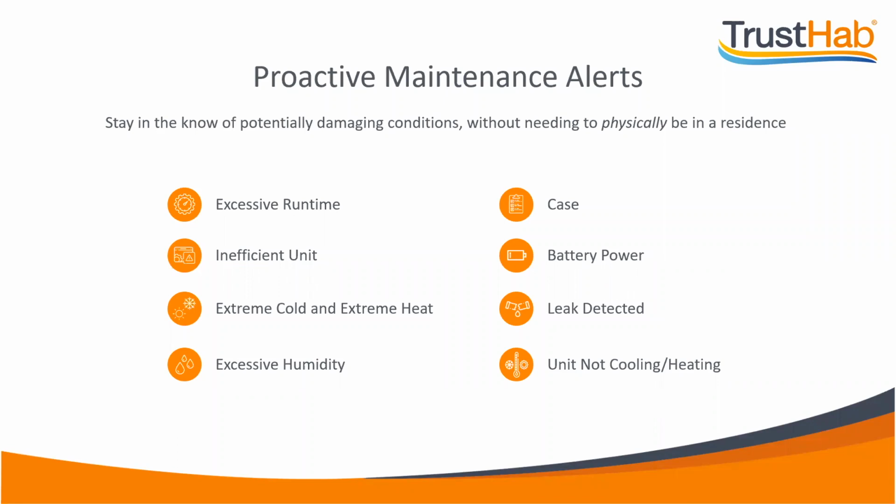Excessive humidity. So just like we've been talking about today, this one has been extremely useful for our partners in helping them find units and parts of their property that may need insulation or weather stripping. High humidity over an extended period of time can cause major issues. Even just staying over the level of 65% humidity over 24 hours promotes mold growth. And our platform helps notify you before it becomes an issue, so you can take the appropriate measures to get humidity down.